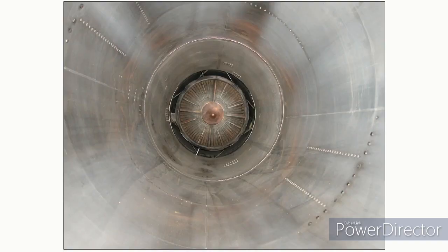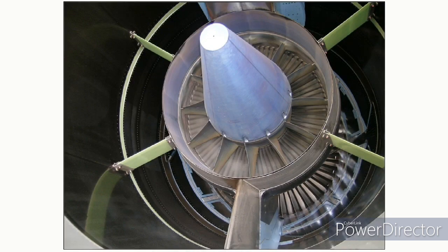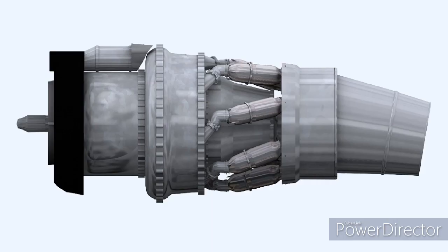The exhaust system of a gas turbine engine is an often underrated part of the propulsion unit, yet its design exerts a considerable influence on the performance of the engine. The gases which discharge from the turbine must exit in the correct direction and at the optimum velocity to provide the thrust of the turbojet engine. While in the turboprop engine, where the thrust is provided by the propeller, the turbine gas temperature and back pressure at the turbine are, to a large extent, dictated by the design of the outlet nozzle.